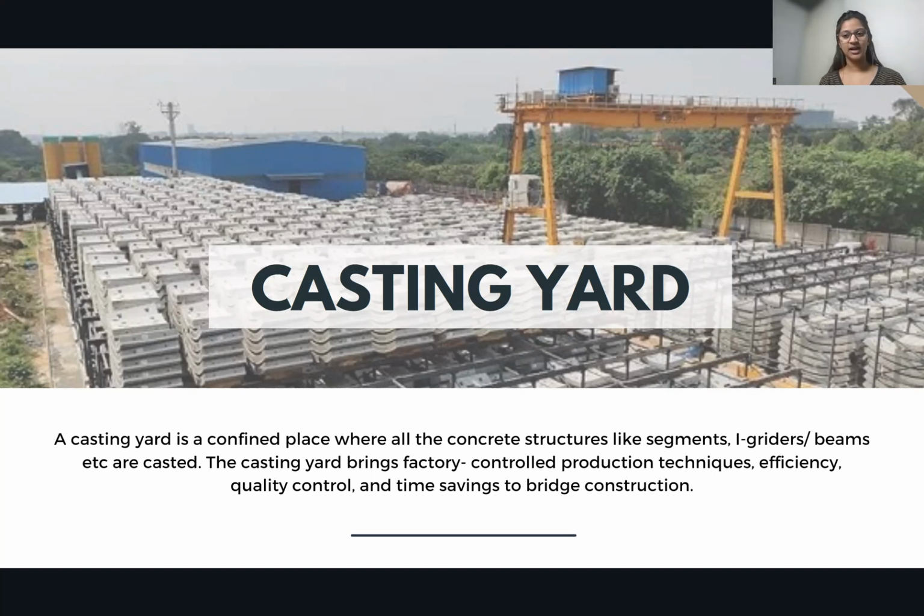Over here, these structures will be kept ready, okay? And at the actual work location, you will have to transport all of these structural units to go and install them there. So the back end work, when the piling work or the pier works are happening, parallelly these segments have to be kept ready so that when it reaches the pier cap stage, these segments will be ready to go and just fix it up there. That is the whole reason, in order to save time, these casting yards are there.